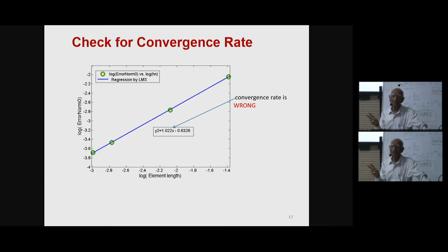Whether they are significant, in some cases they are significant, in other cases, well, I don't know. An error is an error, right? Whether it is significant or not. If you get a temperature rise which is 1/8 of the actual value, or close to 1/8 of the real value, then it's a big error, because your material is softening, so it won't be softening at the right rate.